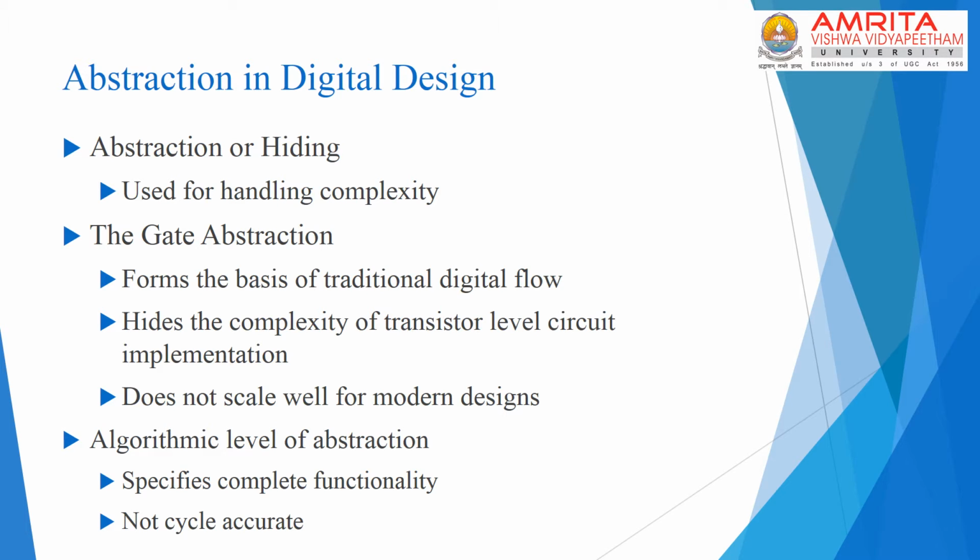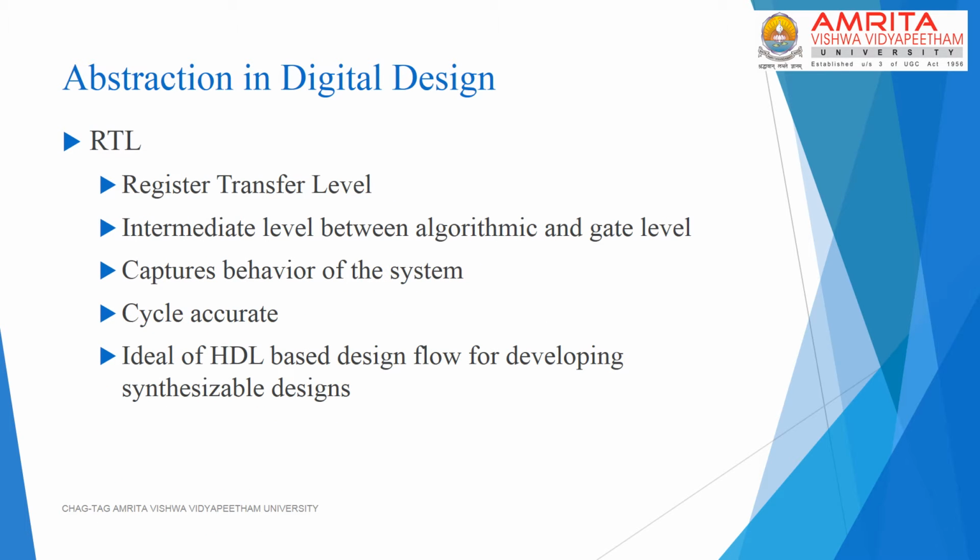On the other hand, we have the algorithmic level of abstraction, which effectively describes the complete functionality of the system, but which doesn't provide any insight into the architecture that will be eventually used for implementing such a system in hardware. Now we come to what this lecture is all about, that is the register transfer level or RTL abstraction. So this is an intermediate level of abstraction between the algorithmic level and the gate level.